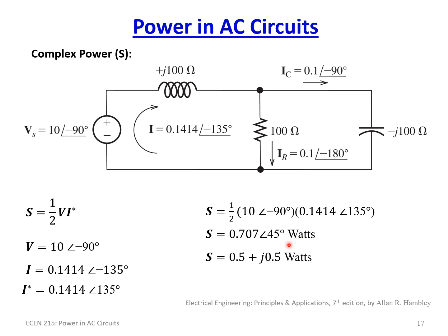Again, complex power, since this is now a vector, a complex value, just has the units of watts. Embedded in that complex value is the reactive and the actual real power. The magnitude of S gives you the apparent power. Broken down here, we've got the P term and the Q term. The P is the real component, which is half a watt, and the Q, 0.5, is half a var, because this is the reactive component.